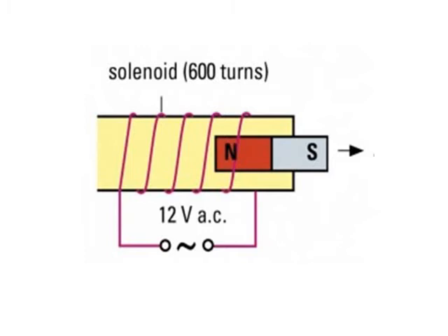So now the method is, first of all, you have to switch on the current. The magnet is placed inside the solenoid. You have to slowly withdraw the magnet. The wire has insulating material, so there is no danger of electric shock. So you have to remove this magnet slowly 2, 3, 4, 5 times. By repeating this experiment, because of the effect of this changing magnetic field inside the solenoid, the magnet now will be demagnetized. So this is another way.